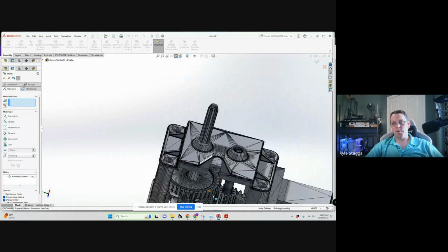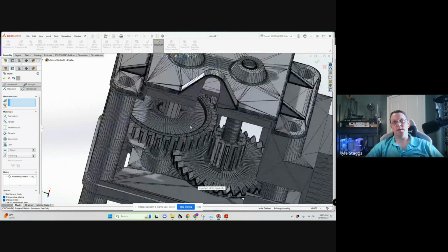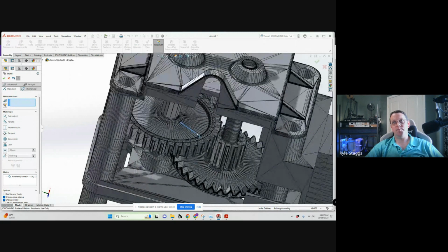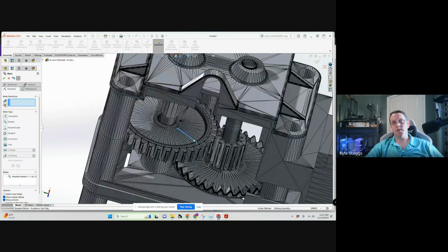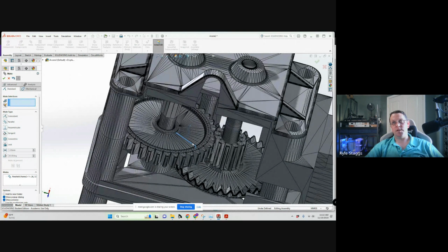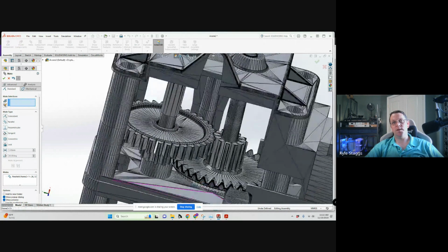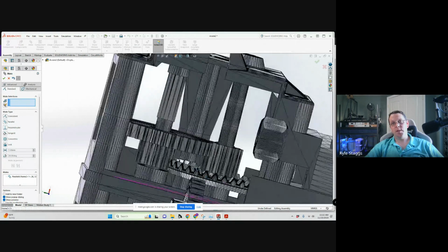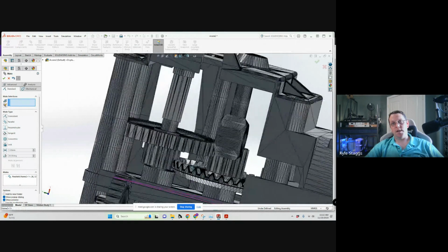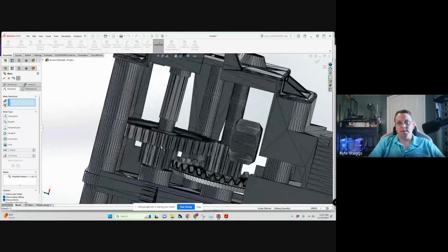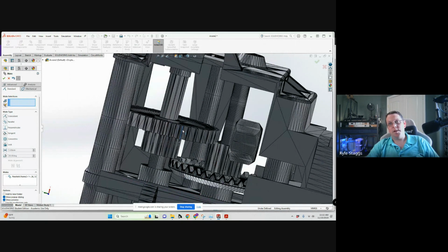So you'll be able to do nice, clean, concentric operations, whereas I won't be able to do those to the same degree, but you'll see here, for instance, that gear can't interface here because there's zero clearance. And if you bring it up, there's not enough teeth to actually mesh.